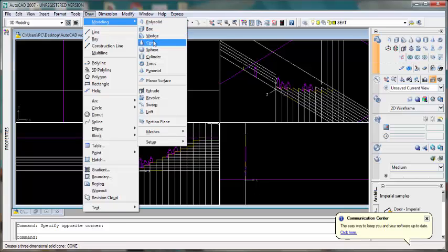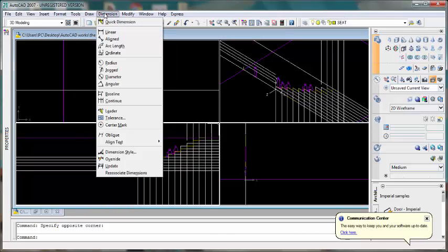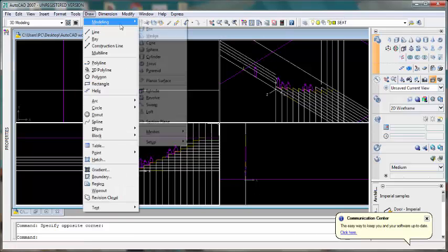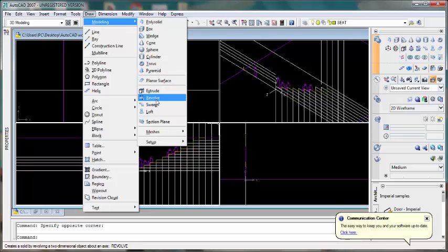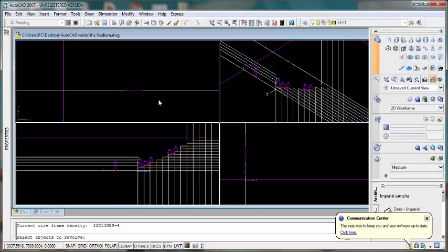If you notice, all of what you're looking at here is still the same things that you're seeing here. This is still polyline, box, wedge, cone. So either way, you can still find your tools. Now I want to use this tool, the Revolve tool. So I'll click on Revolve. Now it's telling me to select object to revolve. I'm going to select this line.